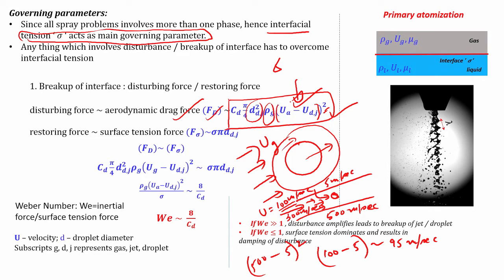Now, what is the restoring force? This force tries to deform the droplet. So, if you are a droplet, you will now start to be deformed in that particular fashion, right. You will no longer remain spherical, okay. But the droplet has an ally, and its ally is basically its surface tension, right. Surface tension always tries to restore; you want to stretch it, it tries to restore you back, right.